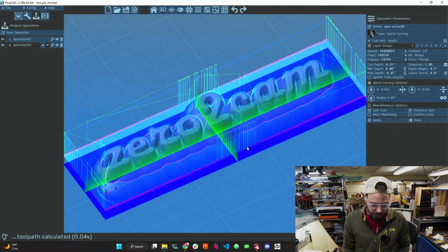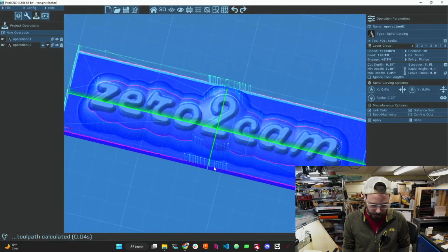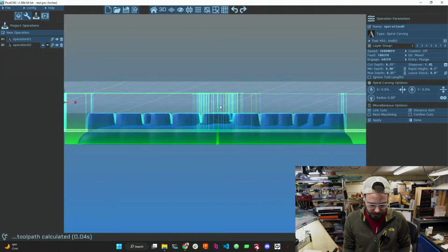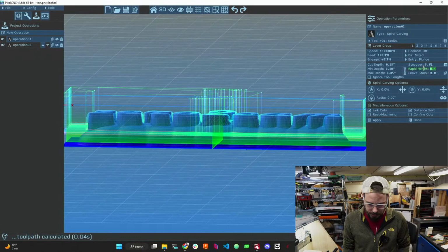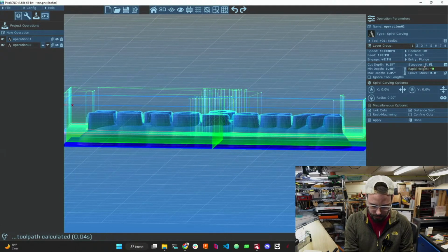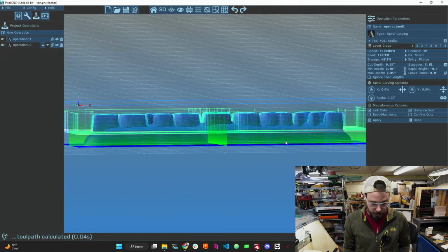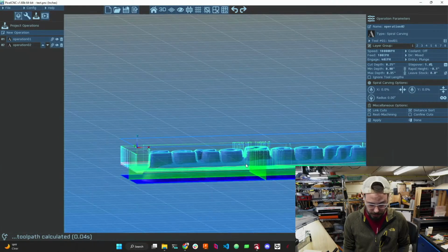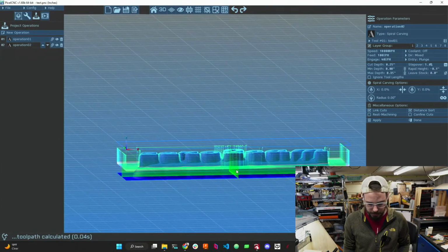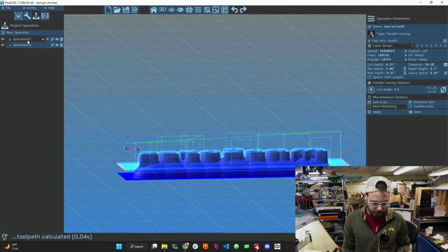So based off what we learned with the B, we're going to get rid of rest machining. So there's a few less lifts in here. And then I'm going to tell it to do a negative 0.1 rapid height and see if it works. Yeah! Because, for two reasons. One, the rapids for the machine are about equal to the feeds that I programmed. And two, all that stock should be gone because of the first pass. First pass machined all that stuff away. So we're going to see how that works. So we'll save the project.